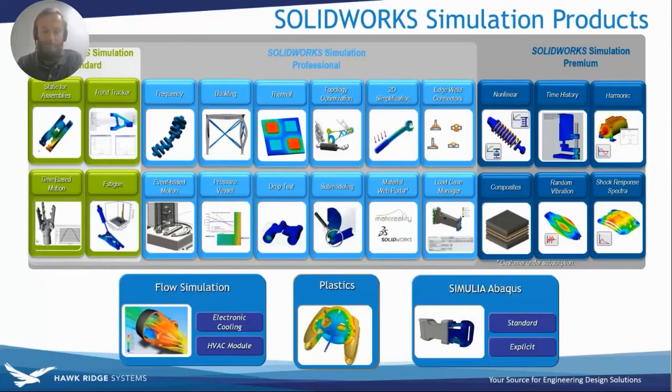So Lucas just had a question. How do I change from first order to second order elements? So all that means is how do I change from draft quality to high quality? By default, it should be high quality mesh. When you're in the mesh interface, when you create a new mesh, there should be an option there to switch it to draft.